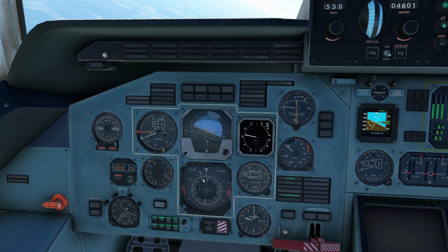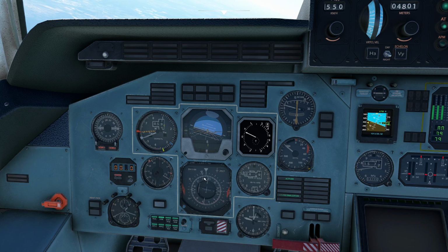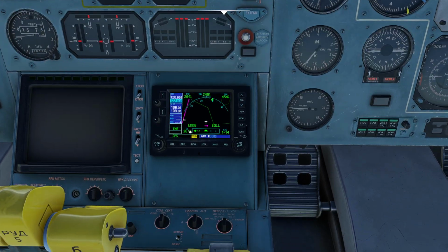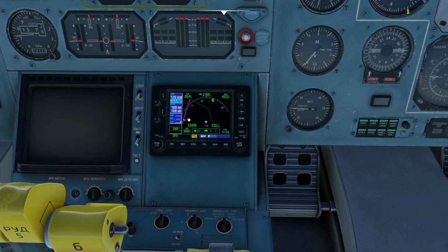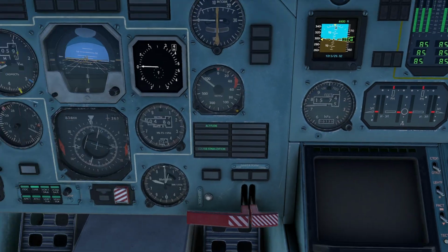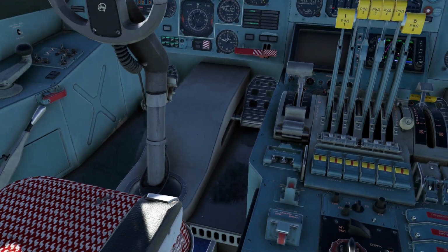Now, this is really important. If we want to have this aircraft lock onto a course, let's say we want to go on 240 and actually lock onto where we're supposed to be, which, by the way, if you want to use a GPS course with this thing, you have to double check to make sure that you've selected your course over here and that you're actually going to intercept it and that GPS mode is selected down here on the left in order for this process to work. So I'm actually going to increase my bank just a little bit here.